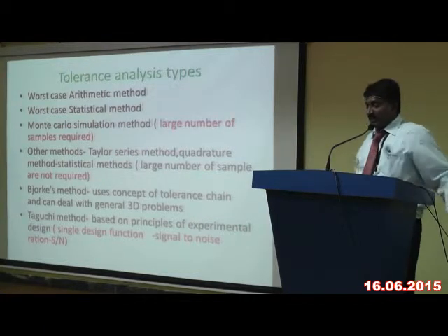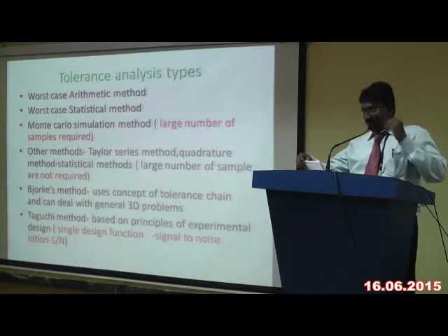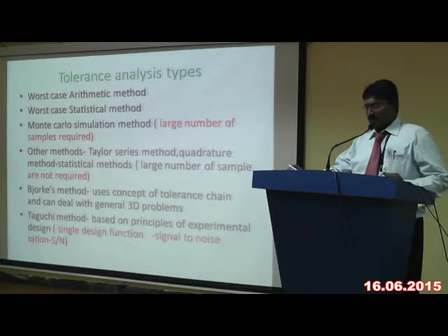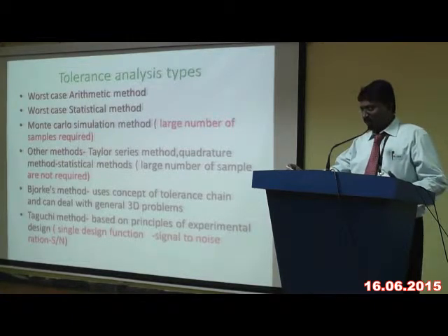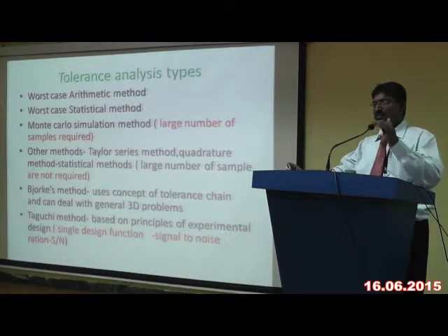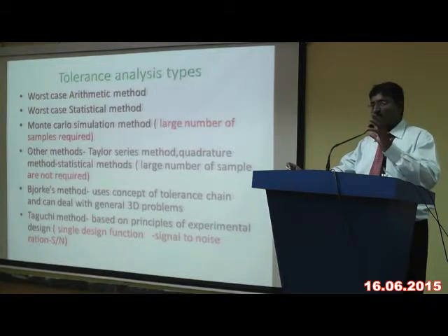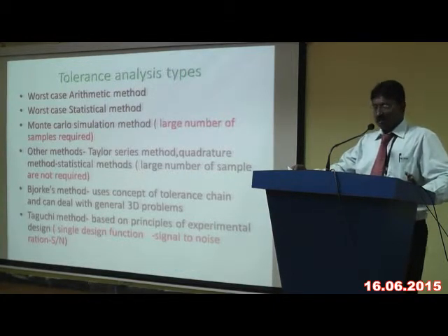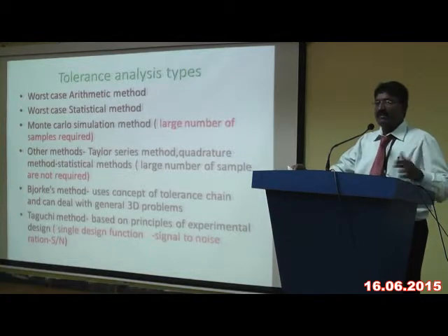So in the statistical method, what we do is we go for the curves, the distribution curves, or the shape of it. It's a normal distribution, a uniform distribution, then quasi-uniform distribution, triangle distribution, and left skew and right skew. When we graph it, we find out the final value, or the best way to go in for the analysis of the tolerances as per the given data.